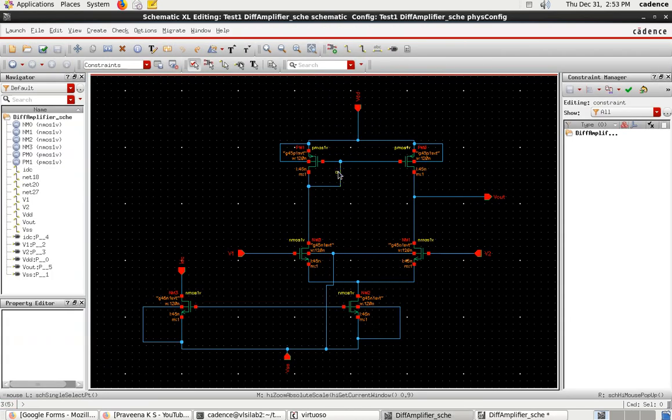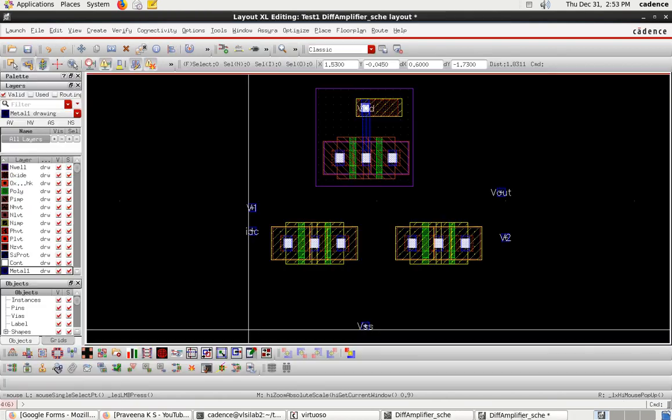If you observe here, see this connection I have given. Now we shall take the output connection. The drain of one PMOS is connected to the drain of another NMOS, so both are interconnected and that has to be given to output. How to check which is the source and which is the drain, whether this PMOS drain or this PMOS drain? Usually we get confused.